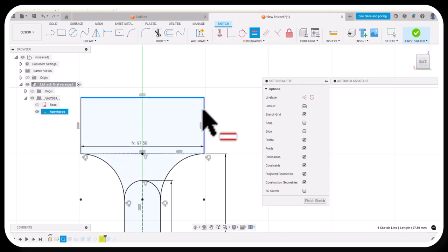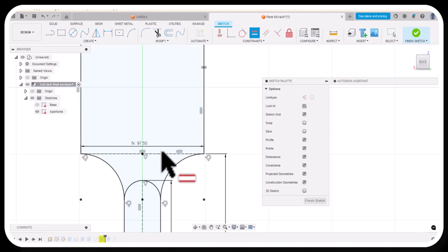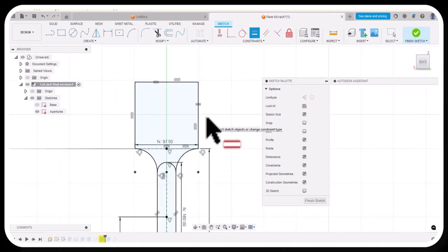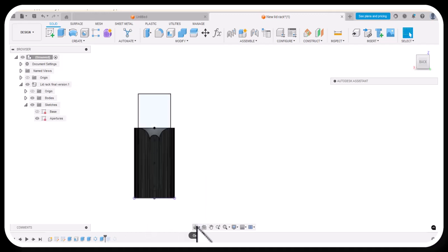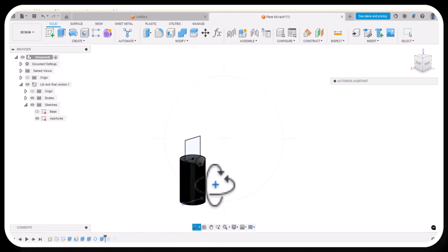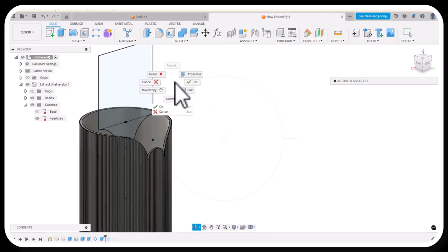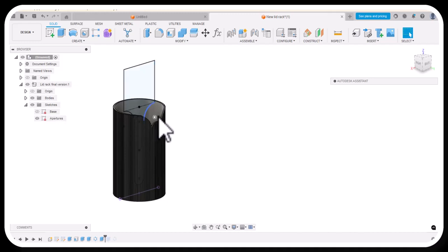And so this is kind of a tip, because a beginner would have difficulty figuring out what in the world is going on here. Why is the software getting confused about that height, that near coincident? It's going out to 16 decimal places, and somehow the computer just got confused on that. So we'll give it a little bit more height on there. That ensures that it's above that edge. And then we'll cut out that slot, and then we'll do the circular pattern.